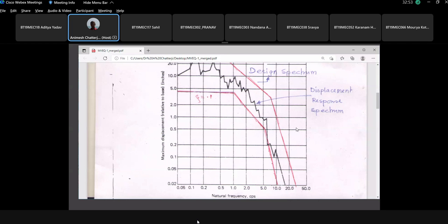So there are liners. The second advantage is that during vibration, if it occurs, these liners will provide damping, and that damping is Coulomb damping, friction damping. In case an earthquake occurs, generally the vibration in any flyover from vehicle movement is very, very small, almost zero. But if an earthquake occurs, the vibration will be much larger, maybe 2-3 inches. In that case, these liners will provide the damping.